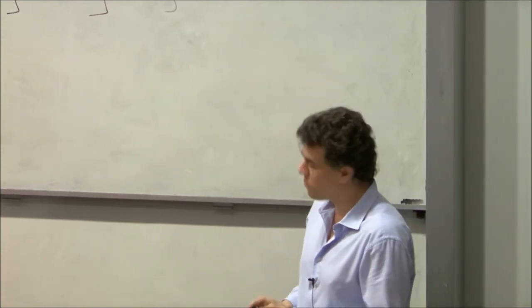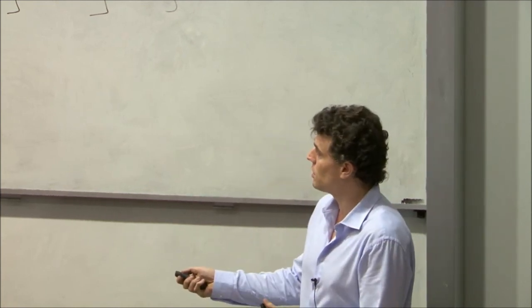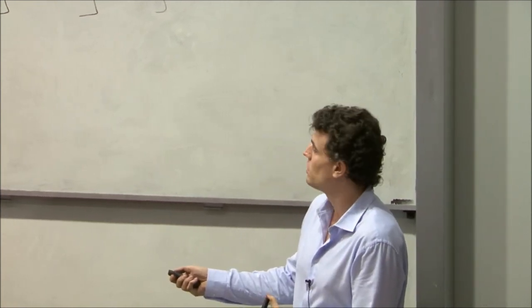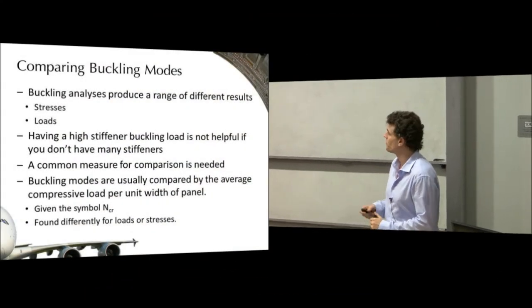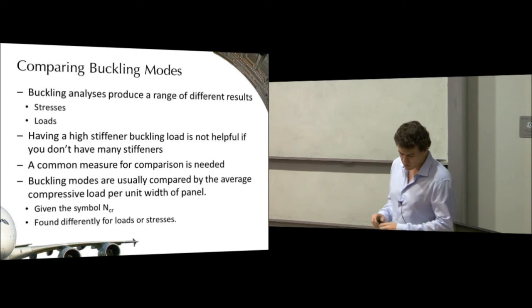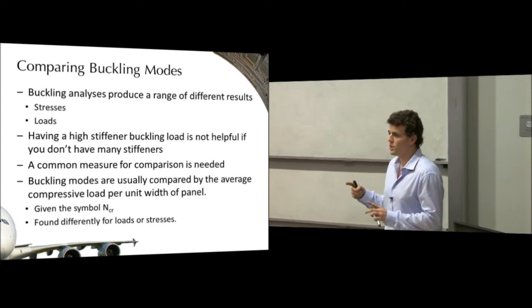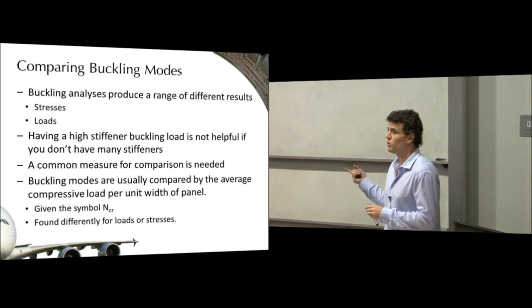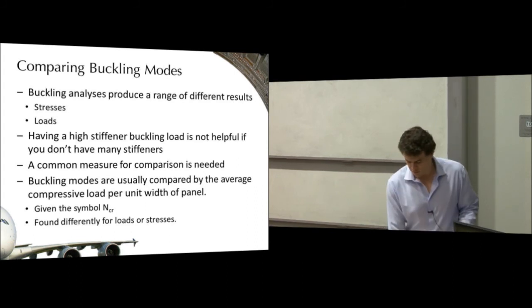And we've seen that n pop up in other calculations before. We've seen the n pop up in composites calculations and some of our other solid mechanics calculations. Now, if we've got a stress calculation, to get to n we need to multiply by a distance. If we've got a load calculation, we need to divide by a distance. So we need to work out what those distances are.